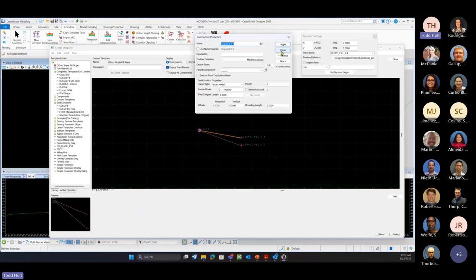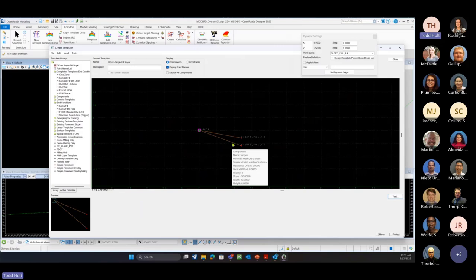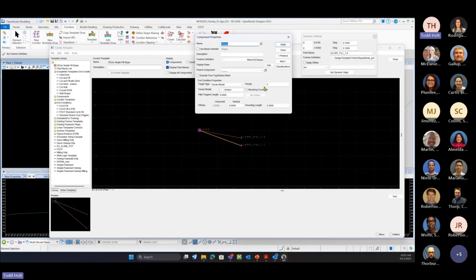If it can't find that, I'm going to move on to my fill slope 2, which is going to be my second solution, but I'm going to use an odd number series to be the second solution in that list. So if I had another fill type solution, that would be 5, or I put that in the number. So the lower the number is the first solution. I'm just moving it to the next solution, and I'm just using odd numbers and even numbers to put in there. It could be 1, 2, 3, 4, 5, or 10. It's just the number that you want it to solve for.